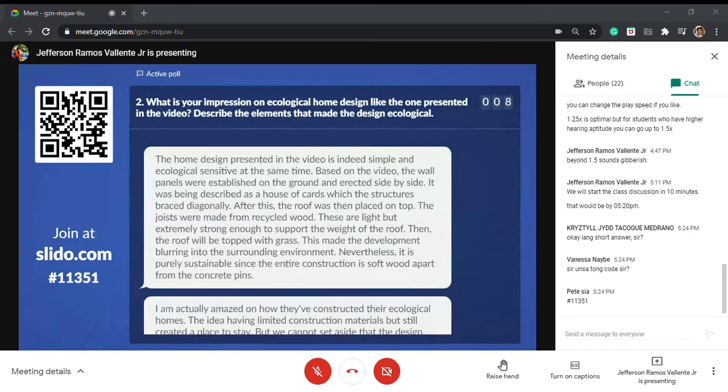Okay, the disruption will come in the form of blockage. If you build a house there and you dig out the underside of the slope, the water that should flow through it when there's extreme rain will just move to the sides. So this movement to the sides can actually cause the structure to fail later due to land movement or landslides. So in that case, stilt construction is ideal. So that is one feature of an ecological design.